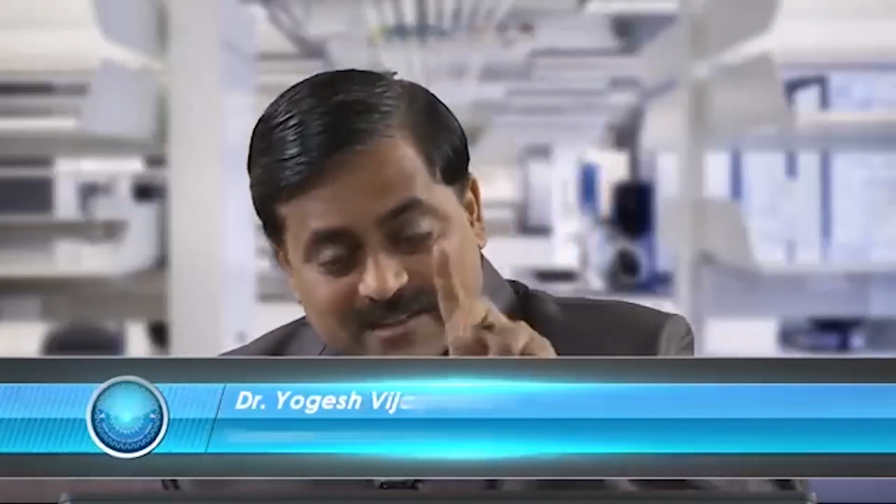This has happened because we have done a pole zero cancellation. Therefore, particularly when we are doing analysis in the classical approach, we should avoid pole zero cancellation. If pole zero cancellation is there, there is a problem, just as we have seen here. The problem is that your order has been reduced. The system is stable, but in real time the system is unstable.